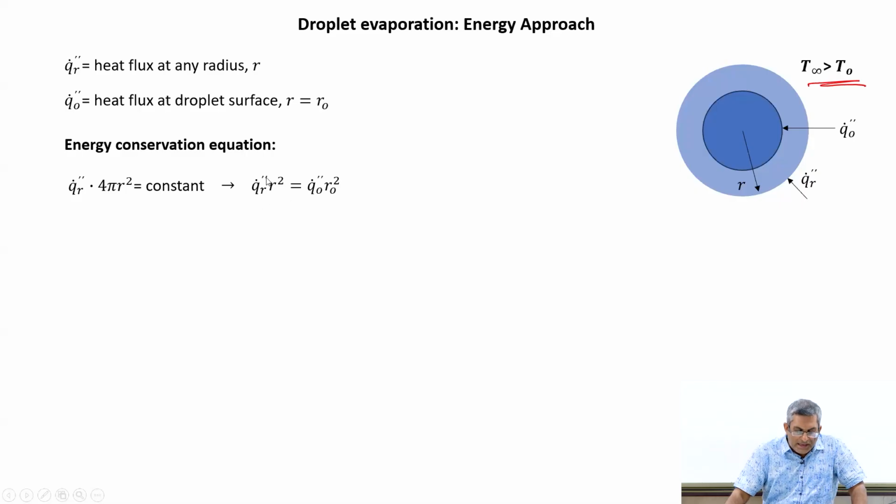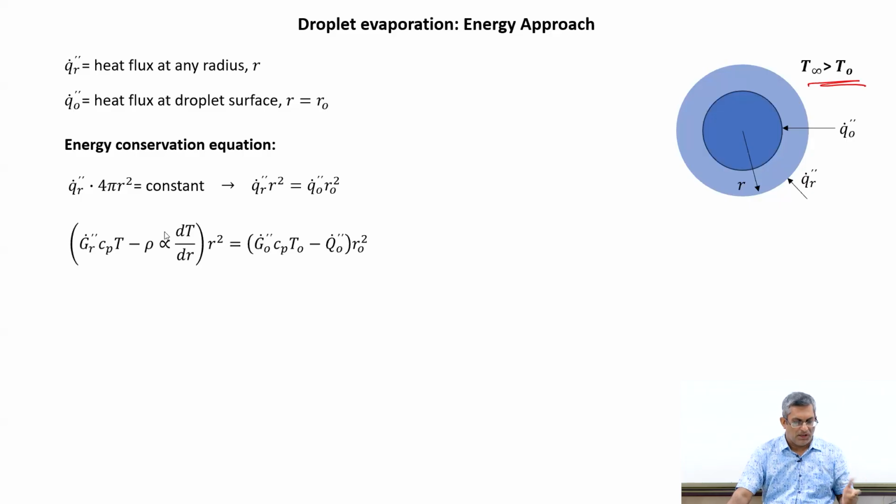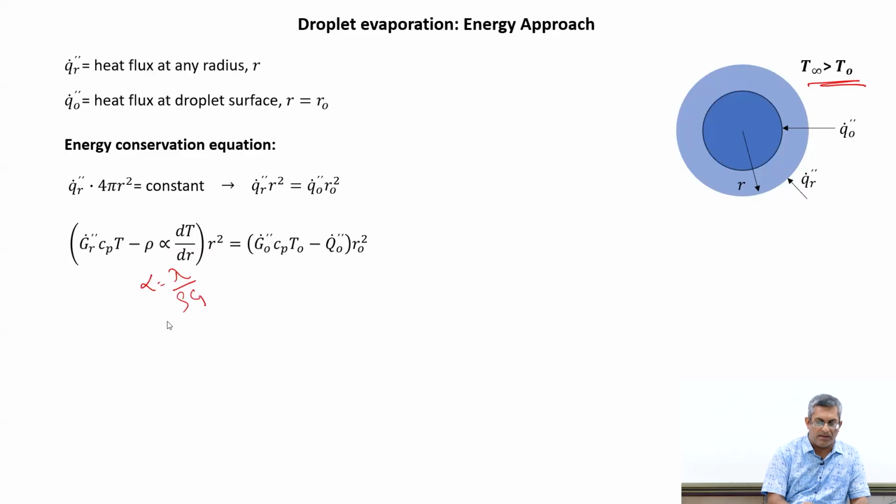Now again, this heat flux that you see has two parts. One is the convective flux, one is the diffusive flux, as in the case of mass flux. So this is the convective flux part and this is the diffusive flux part. Okay, so now what is alpha here? Alpha is the thermal diffusivity, thermal conductivity lambda divided by rho Cp.